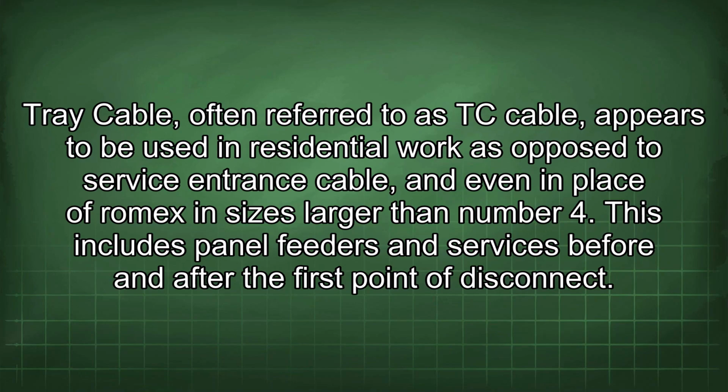Tray cable, often referred to as TC cable, appears to be used in residential work as opposed to service entrance cable, and even in place of Romex in sizes larger than number 4. This includes panel feeders and services before and after the first point of disconnect.